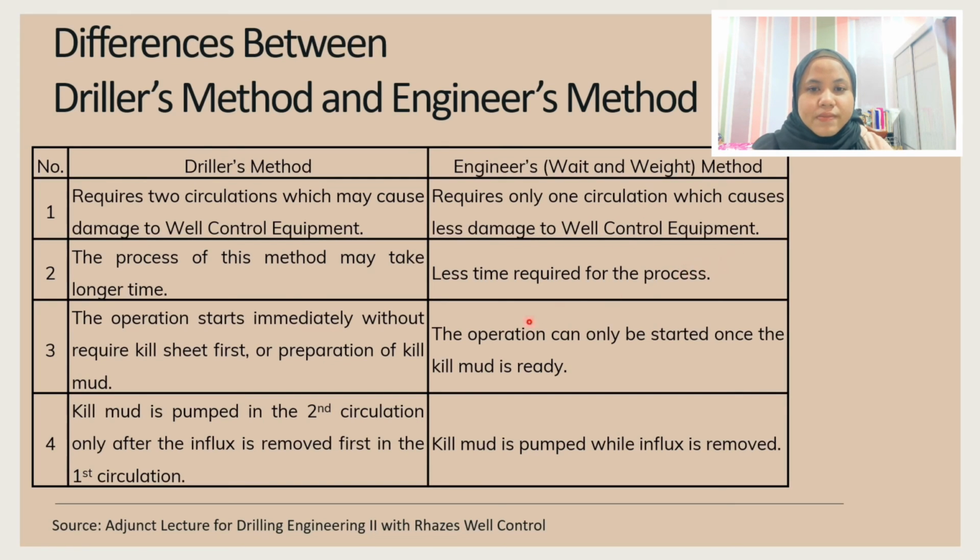The next difference for these two methods is that the operation for driller's method can start immediately without requiring the kill sheet first or preparation of kill mud, as it can be done during the first circulation because the kill mud will only be used in the second circulation. However, the operation of engineer's method can only be started once the kill mud is ready.